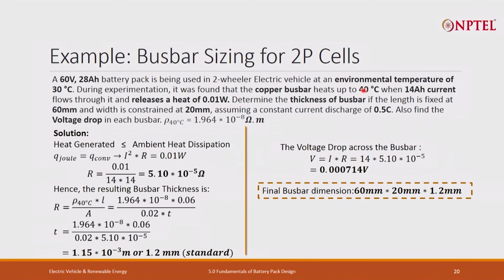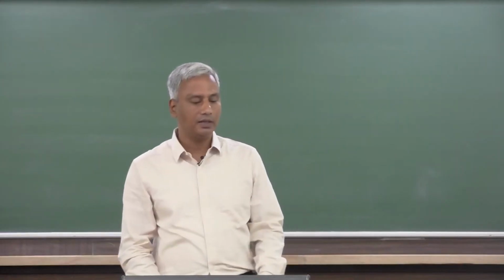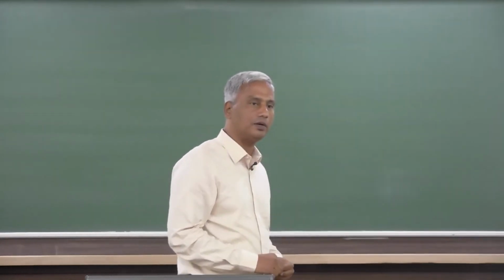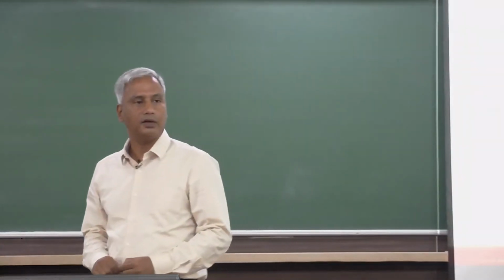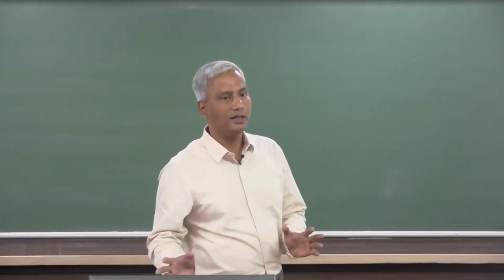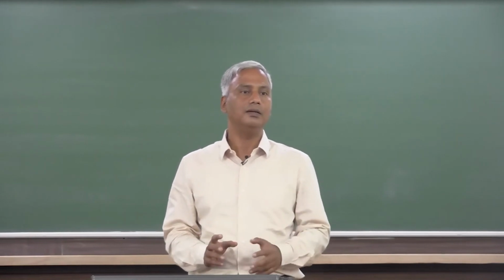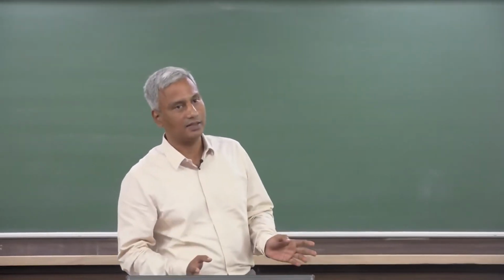So, let us move ahead with the design criteria. Whatever we have talked about, we have solved one example problem, bus bar sizing for a 2-piece cell. There we tried to find out what could be the thickness of the bus bar and what could be the voltage drop. Obviously, this was a simple question in the sense that we have given you all the data, the temperature and the resistivity at the same temperature.